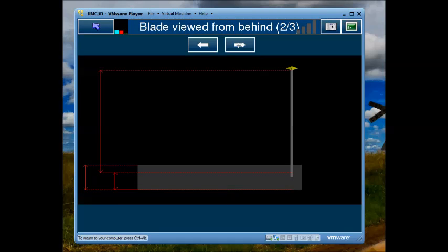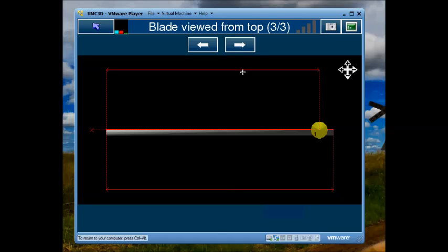So you go for page number 2, and then here you make the definition of where the mast height and the blade height and the blade wear. The default values here are quite often okay to use, so you basically don't need to do anything for the simulator. If it would have been a real machine, of course you need to add the proper dimensions here. Same thing for the antenna location, on what side of the blade it is. Down here you state the width of the blade, and on the other line here you state the distance from the left corner of the blade to the antenna.